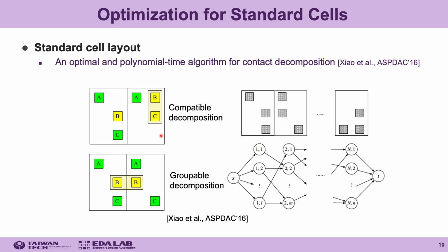And for each pair of adjacent cells, if a coloring solution of the left cell and that of the right cell is originally compatible or compatible by considering DSA grouping, such as the 2 examples shown here, an edge will be added between the vertices representing the 2 coloring solutions. So for a row of cells, a solution graph can be constructed as an example here, and a feasible solution exists for this cell row if a path can be found from the source node to the target node.